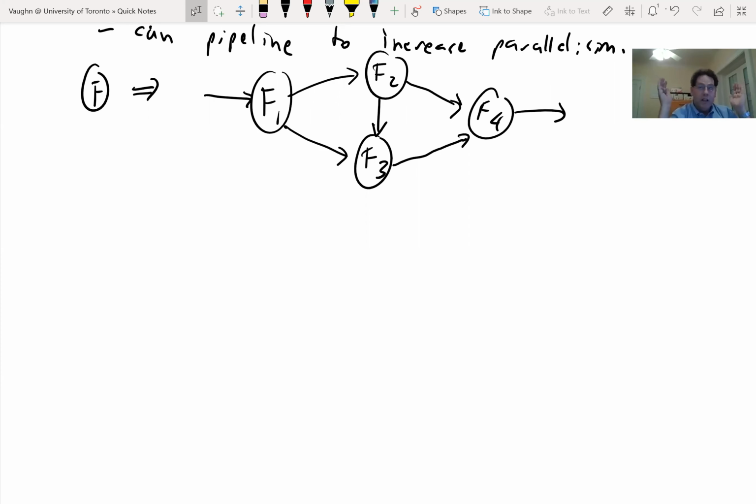So it's the first thing you want to think of when you're trying to get higher performance out of an FPGA design. And it's basically because FPGAs have tons and tons of registers. So the cost of pipelining is very low. You usually have extra registers lying around anyway. And it keeps your data very local. Your data is distributed on all these wires.